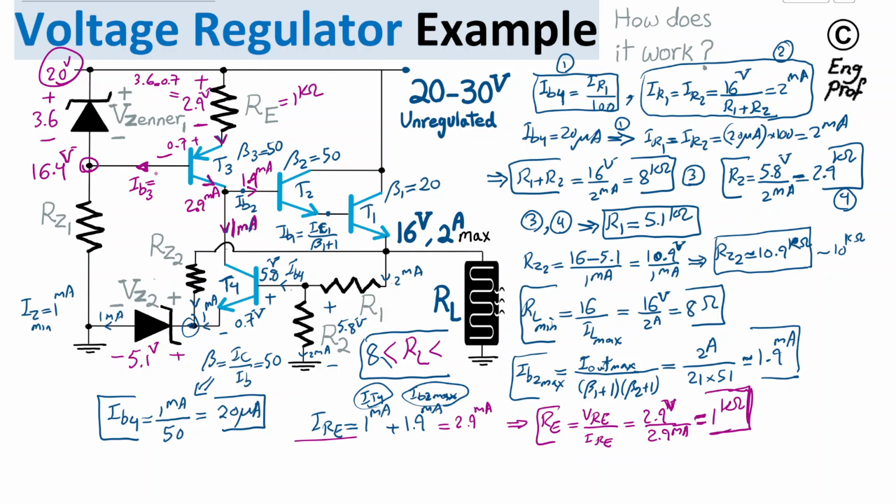That is emitter current, collector current, sorry, this is collector. So collector current 2.9 divided by beta, which is 50. So that is on the order of 3 divided by 50, roughly 58 microamp. So you're talking about 58 microamp that is going this way.